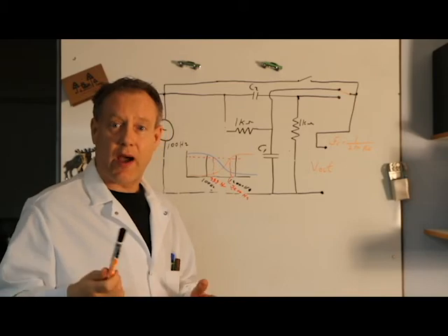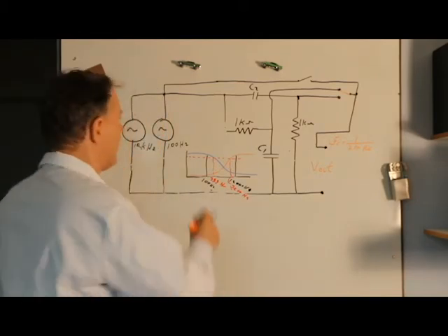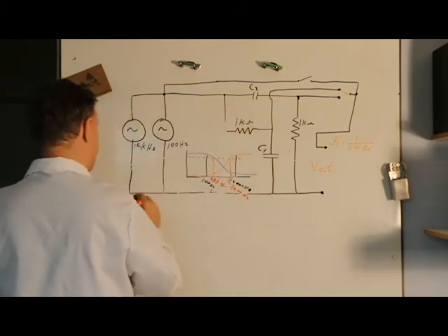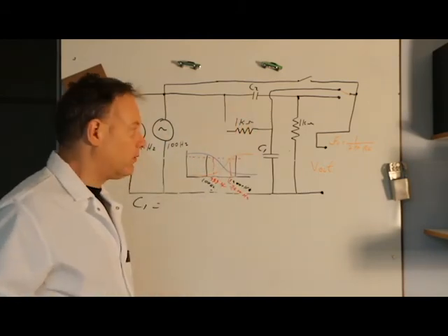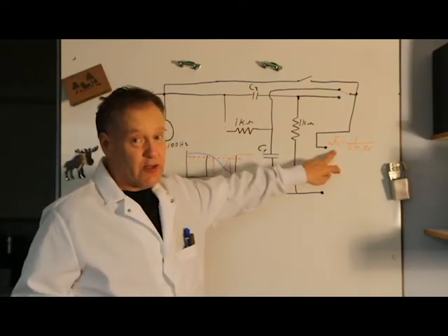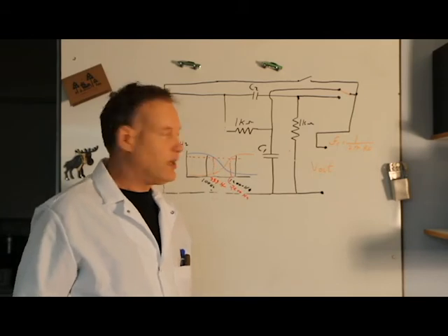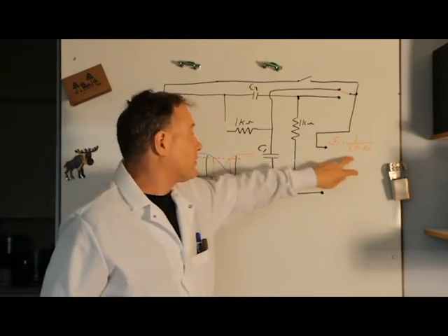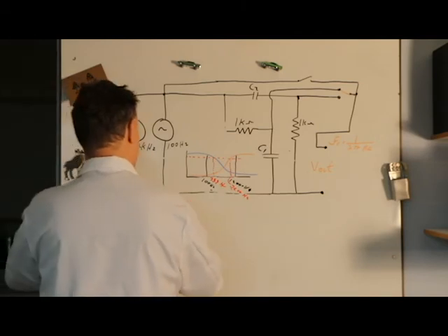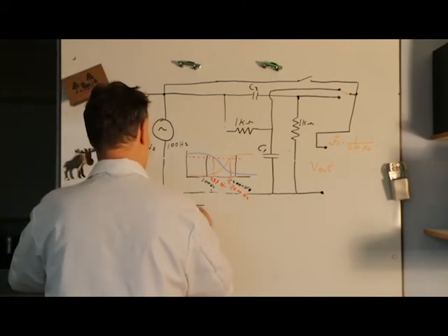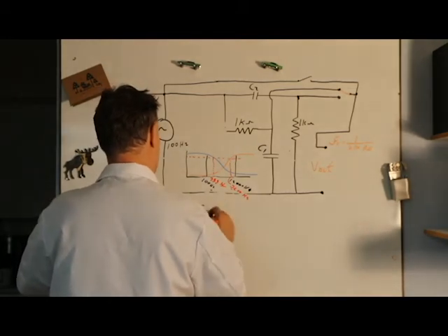Cool. So what I can do next is do the math and calculate what capacitance is required to make those corner frequencies happen. We've got C1 and C2. For C1, what's the formula? That's the formula for calculating the corner frequency. I know the corner frequency; I just want my capacitance, so I can rearrange that. That's going to be this over 2 pi, and then I put my corner frequency in and my resistance.